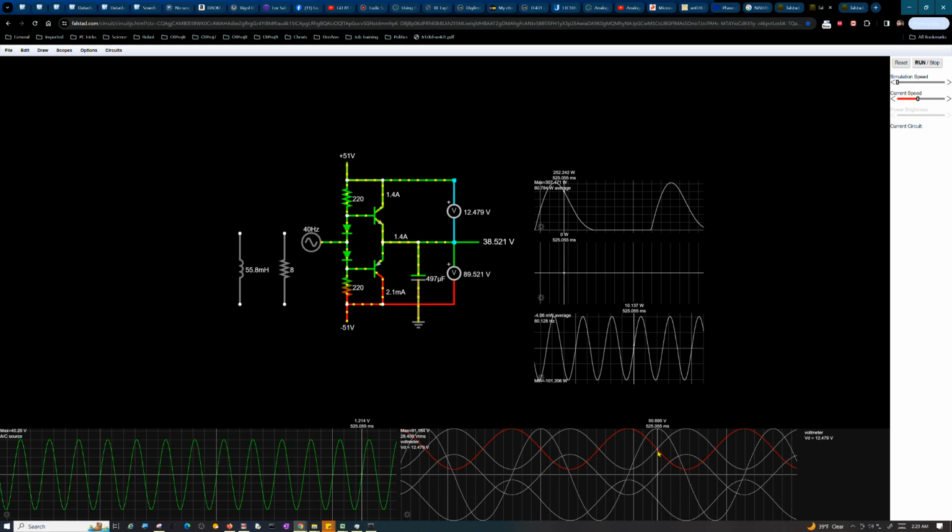Okay, now what's the voltage at peak current? It's about 50 volts. So in some ways what he's saying is right, that is, at peak current, the voltage across the transistor is about equal to the supply rail. But the thing is, that's not the peak voltage across the transistor. The peak voltage across the transistor, as you can see again by the red trace, is actually 91 volts. And that's because this transistor starts turning on when this is fully off, so that's where all the current is basically coming from.